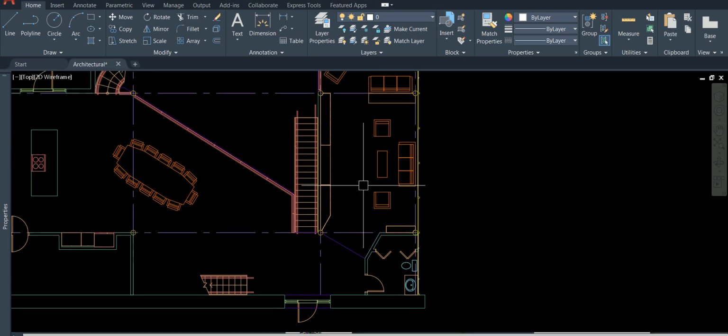I have two or three more methods of selection, because in AutoCAD, if you're manipulating or modifying any object, you need to know how to select the object, isn't it? Yes, I agree, those three basic ones: picking, which is called manual selection, another one is crossing, another one is window. What you learned extra was a fence, isn't it? Now you're going to add and remove. I'm going to teach you some more.